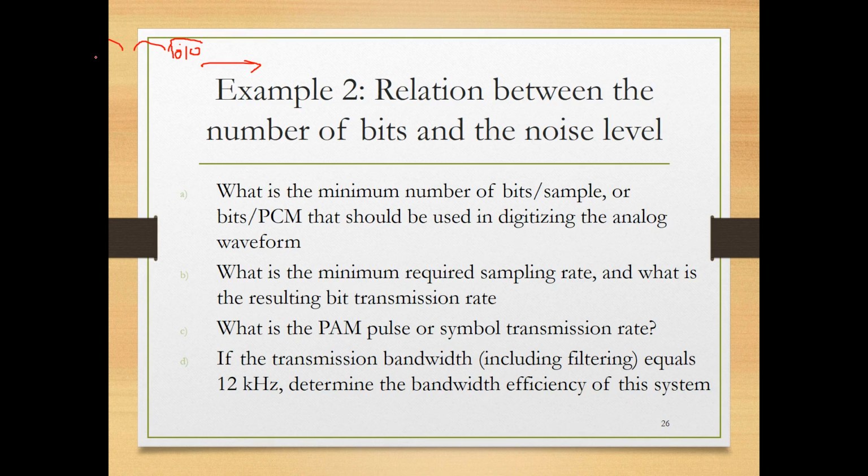Then what would be the rate? Take each 4 bits and convert them to one symbol. What would be the symbol rate? Divide the number by 4. I obtained the sequence of zeros and ones, which represent the analog signal. But then I want to modulate it. I want to transmit it over a channel. I have 16 levels for the pulse amplitude modulator. If I have 16 levels, this means that each level requires 4 bits. You can encode 4 bits into each level.